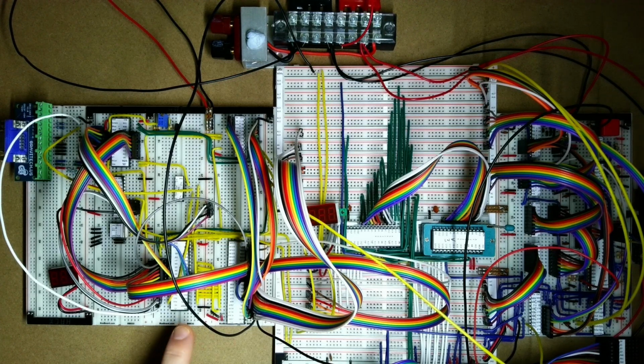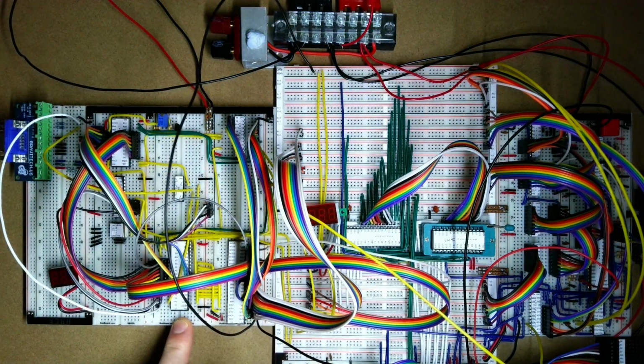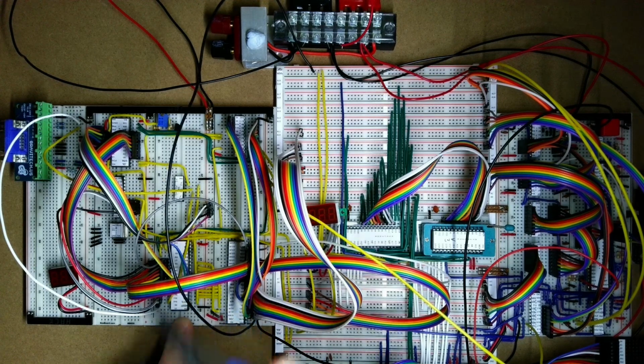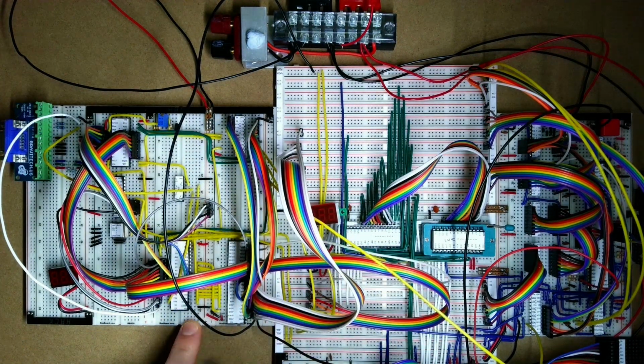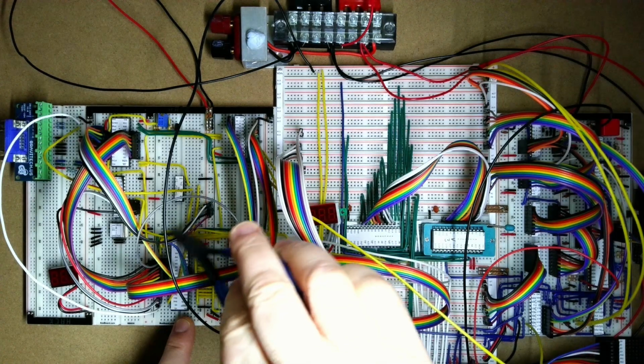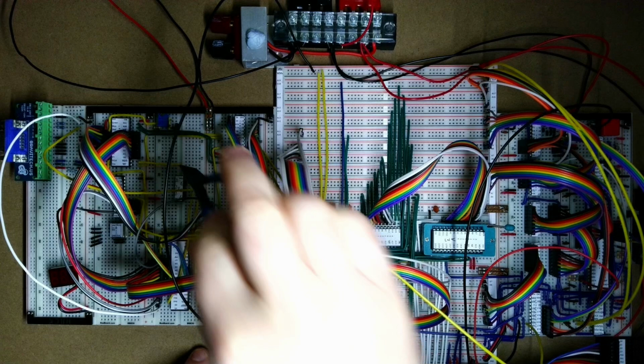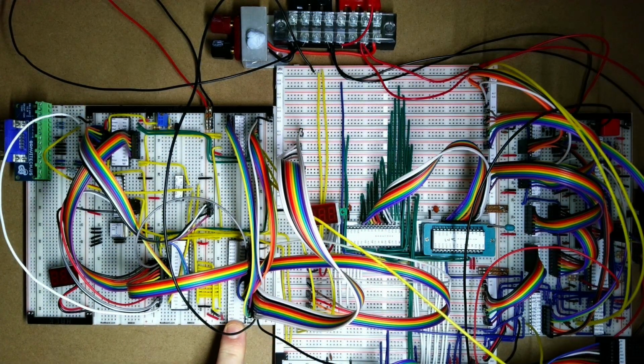What I might do to start with, similar to what we did in the previous video where we tied the video DAC to some of the CRTC address lines, is tie the address lines to the ROM here before we wire in the character latch. All that will do is allow us to check whether the shift register and the character generator ROM are hooked in properly, and that'll generate 256 characters across the screen as the CRTC goes through the address lines. Then once we add the links from the character latch into there, we should be able to update the programs to set the video RAM contents and do some sort of test patterns and things.